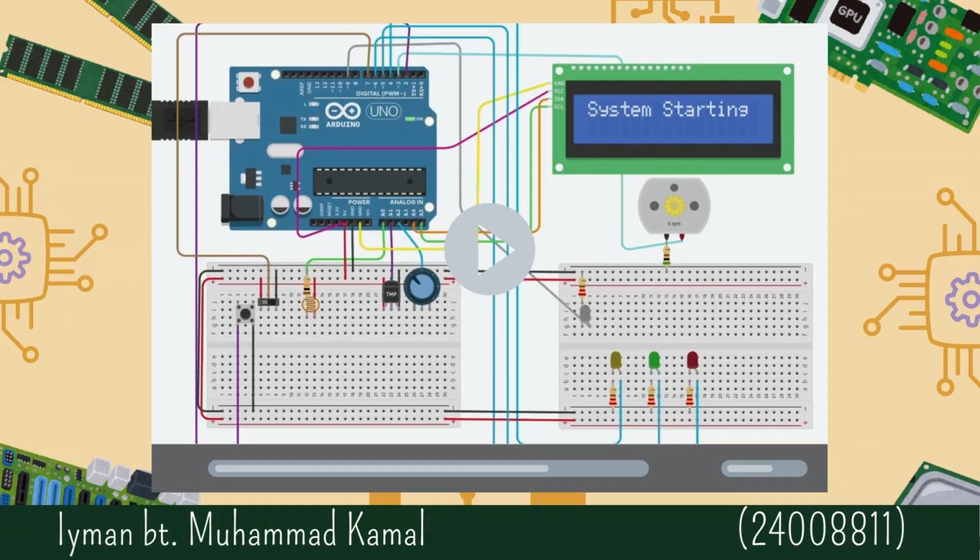At the start of the system switching on, it is first set to be in the automatic mode. In the comfortable zone of temperature between 19 to 30 degrees and humidity between 30% to 50%, the green LED switches on and the fan runs at low speed. Both conditions must be met simultaneously. When the temperature is lowered, the cool zone is entered and the yellow LED switches on. The fan switches off. When the temperature is raised, the hot zone is entered and the red LED switches on and the fan runs at high speed. Temperature is set to be the first condition to check.